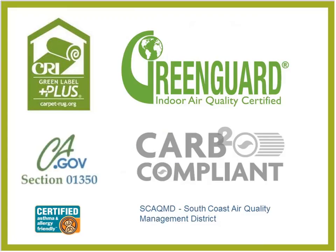So, continuing to find ways to reduce the VOCs and other toxins coming off materials. First, you've got Green Label Plus, and we recommend all carpeting follow this indoor air quality measure. And then you've got Green Guard, which is a certification for many different green materials, insulations, and other components of the home. You can get a Green Guard label on those and review them for air quality certification.